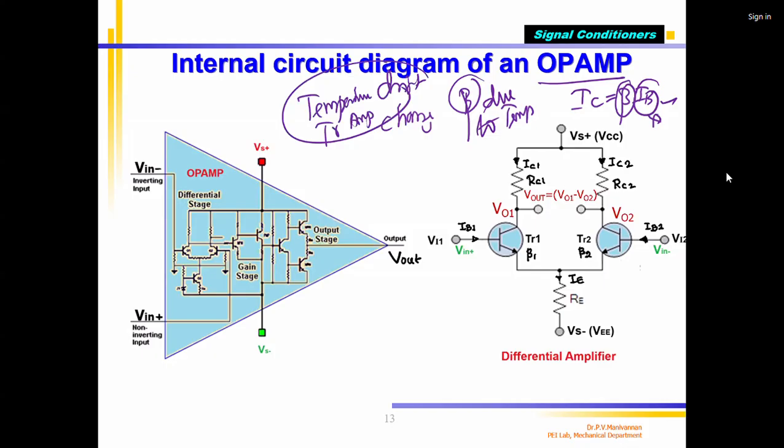But inside the op-amp, again you have the same CE configuration, only multiple stages are there. Correct? So suppose the temperature of the op-amp was 30 degrees. At that time, the gain was 100, 100, 100. What is the total gain? 5 stages are there: 100, 100, again 100, again 100, finally 100. According to total beta, this is beta 1 multiplied by beta 2, like this up to beta 5. Each equal to 100 gives 10 power 10. Correct? So that is what we call AD, note down.